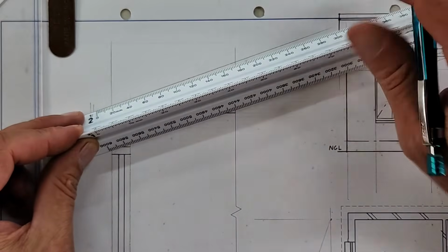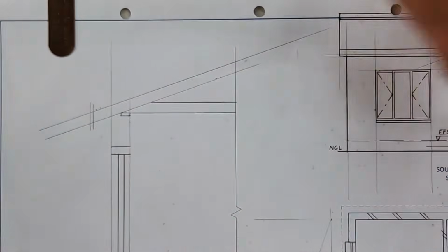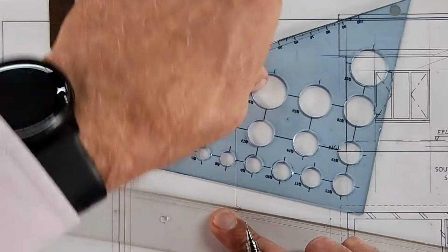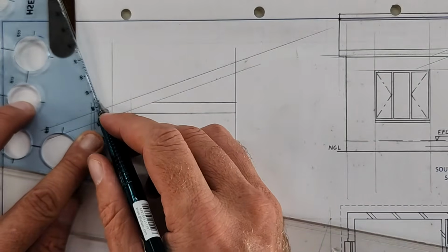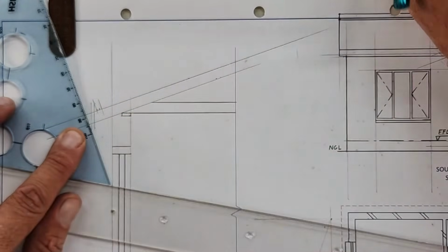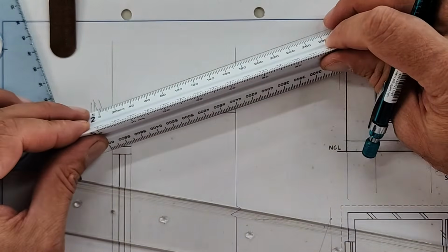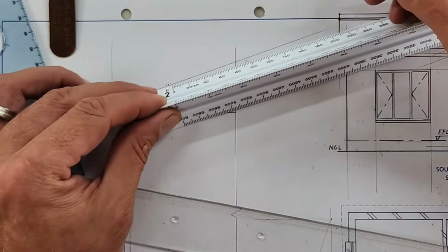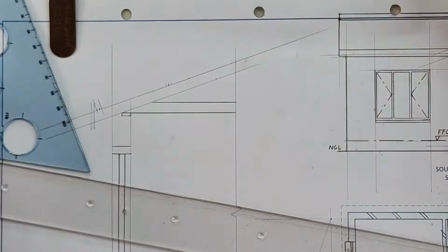Alright, my purlin heights. The first purlin is right in the corner here, and that purlin is a 75 by 50. It is at 90 degrees, so make sure you've got your triangle. You flip that, and in that corner is my first purlin. Then center to center, that center is at 950. There's my next purlin. I can do the sides of that. And then another 950. So look here, you're not going to have your third one in there.